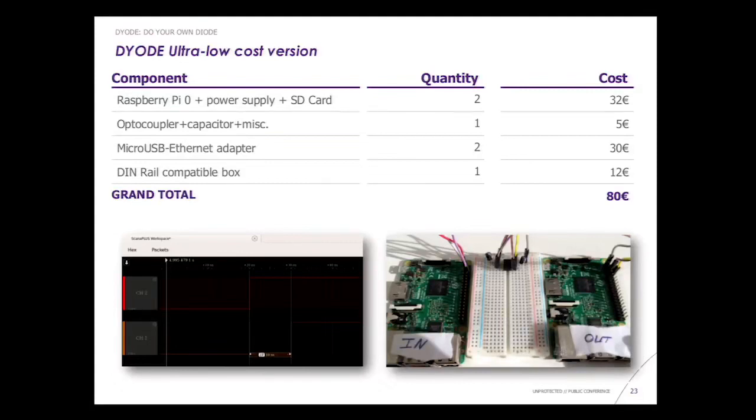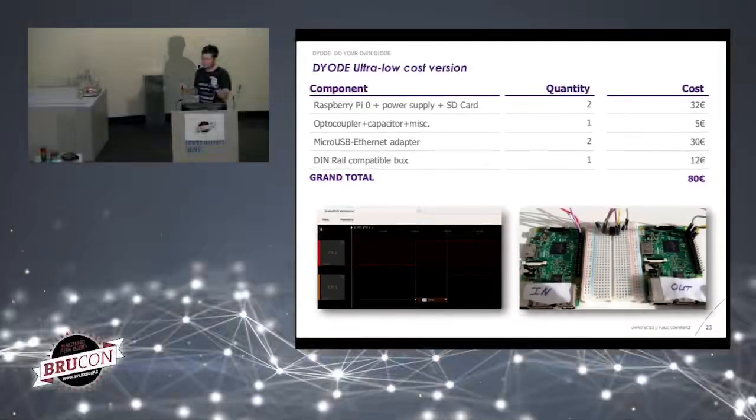On the right side, you can see a breadboard with all the required components. It's quite easy, and there's two capacitors and one optocoupler. And on the left side, it's a logic analyzer capture, but I don't think you can see it properly. It's just to measure the time that the information takes to go from one side of the optocoupler to the other one. It's about 10 nanoseconds, something like that. So depending on the optocoupler that you buy, you will have some speed limitation.